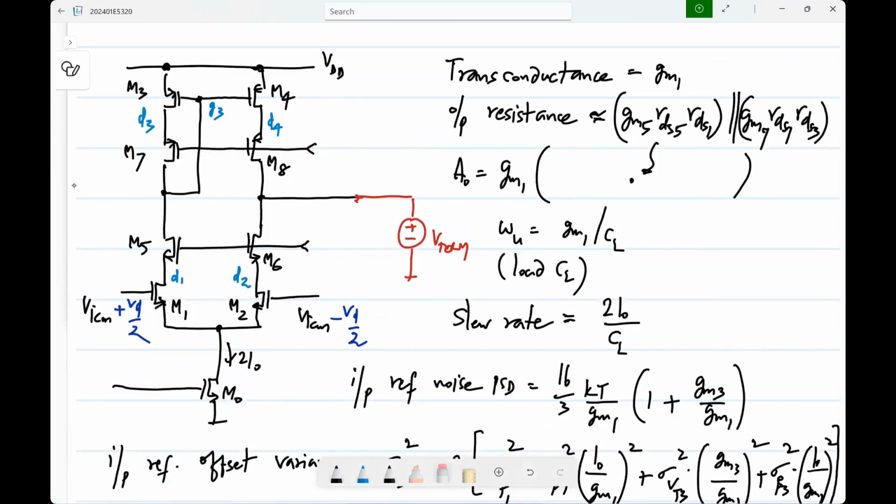Okay. So now how many parasitic poles will you have? What do you expect? Six. Why 6? Not 3 on each side. There are 5 extra nodes, right? D1, D2, D3, D4, and G3. So expect 5 poles. Now it could be that the poles at D1 and D2 are identical, because they have the same parasitics and so on, but you get many more extra poles.